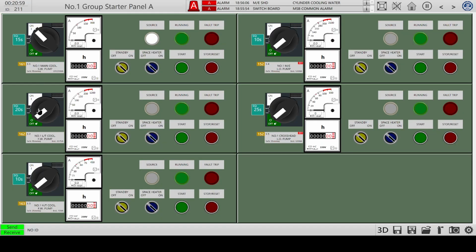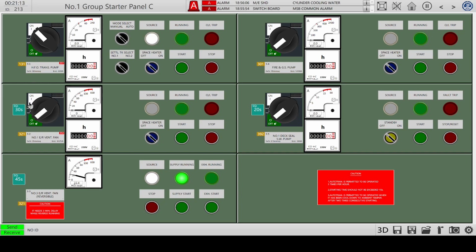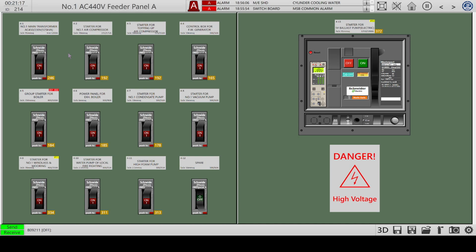Let's enable some more breakers so we can set up the cooling. The cooling is in two circuits, as you know. First, the seawater cooling, that will cool the freshwater cooling to reduce corrosion in the pipes. The fresh water is used to actually cool all the systems.